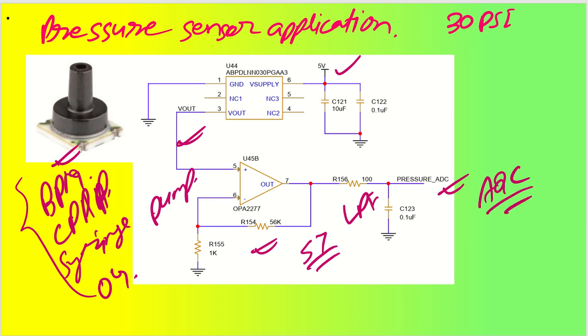Okay. As you have seen, there are a lot of sensors and a lot of monitoring voltages that have to be monitored through ADCs. So we have a requirement of several ADCs on my microcontroller, and almost all the ADC channels of your microcontroller will be utilized. In that case, we do not use the internal ADC in the microcontroller. Instead, we have a choice of using an external ADC also. So in this session, we'll try to understand how we can connect all these outputs to my external ADC as well.